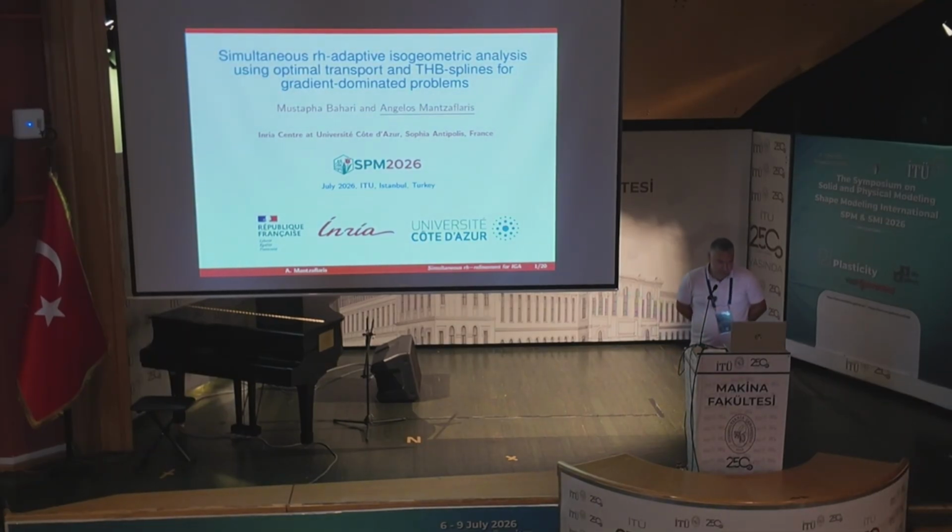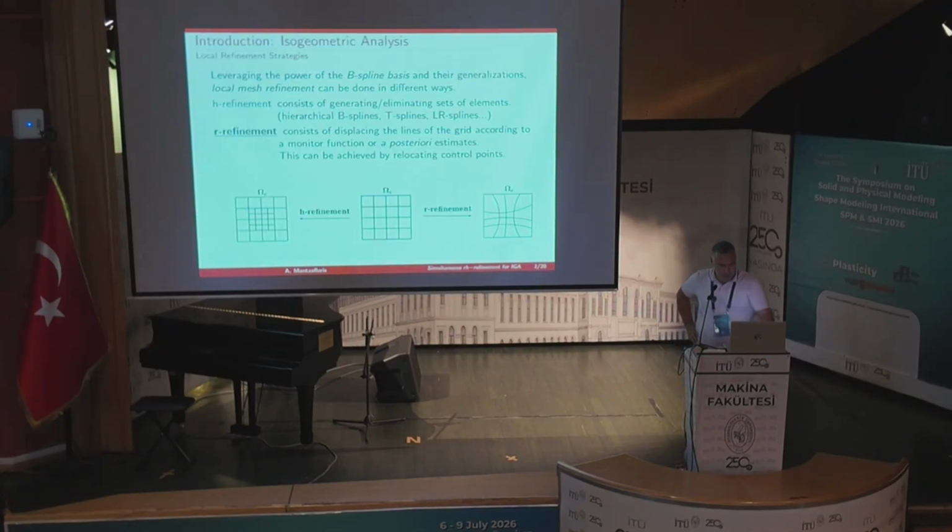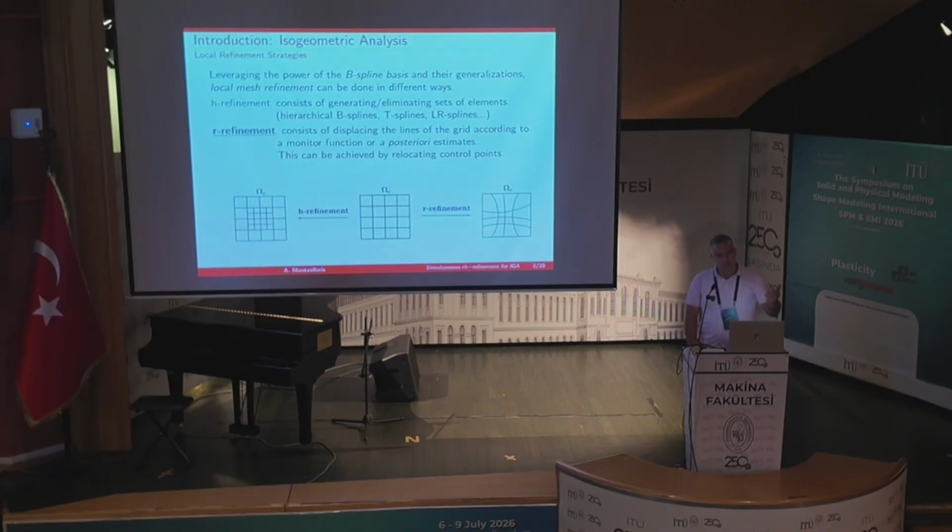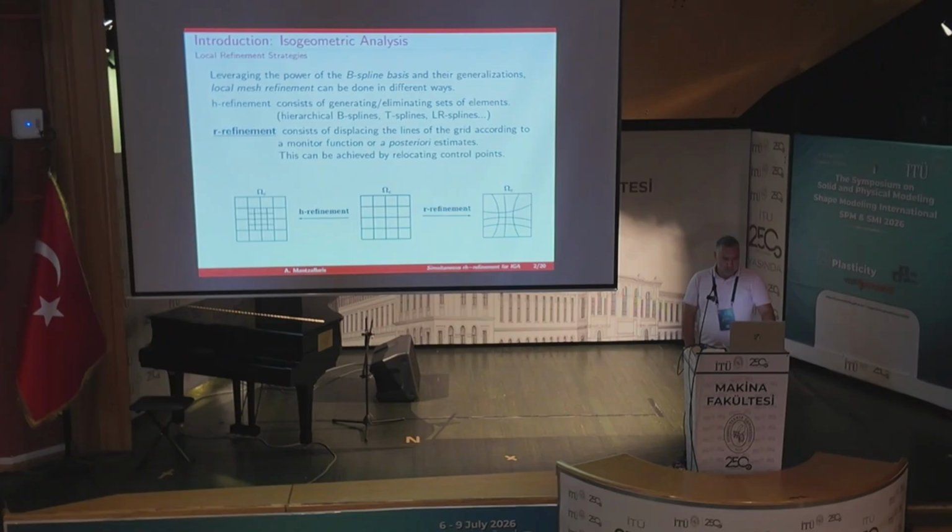So our paper is about simultaneous RH adaptive isogeometric analysis using THB-Splines. We didn't have an introduction to isogeometric analysis in this conference up to now, and nor will I make one. But briefly speaking, we want to use B-splines and splines in general in numerical simulation. So we regard the spline spaces, the spline basis functions, as functions for finite elements. In this context, there are a lot of developments and technology to do local H refinement, so to locally enrich the mesh, like the mesh you see here on the left.